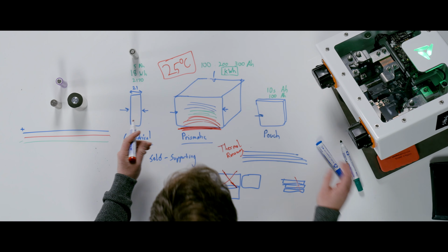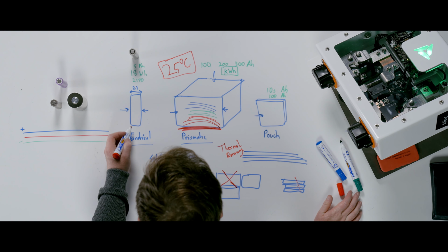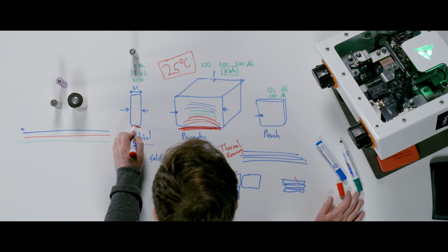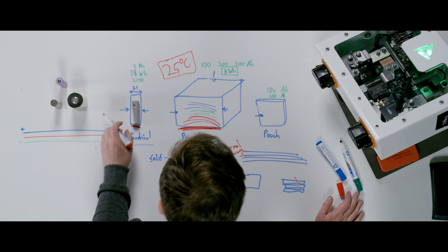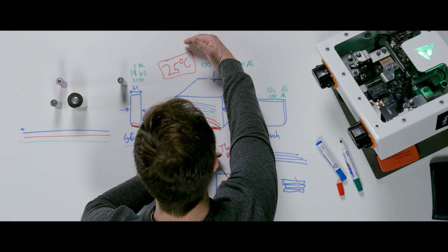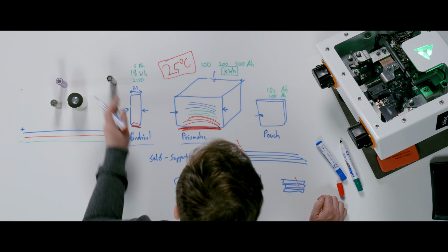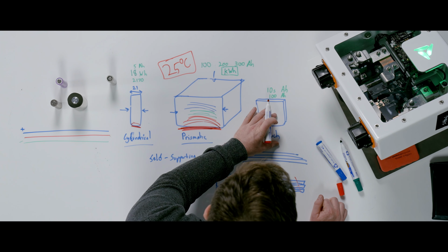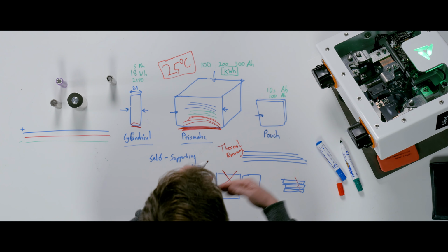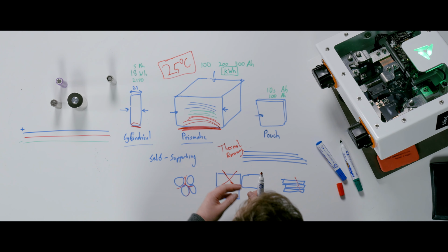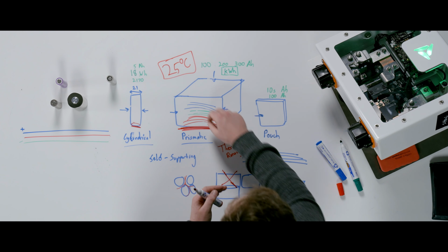With the cylindrical cell, because it's physically much smaller, it's much easier to do it here because the gradient on something that's this size versus something that's almost as big as this table is much, much lower. So cooling smaller cells is a lot easier. And also, when it comes to pouch cells, you have a similar type of issue to cool practical cells. So big cells, harder to cool, harder to get the energy in and out of the core, especially when the heat is internally generated, because these internal heating effects result in very strong temperature gradients inside of the cell.